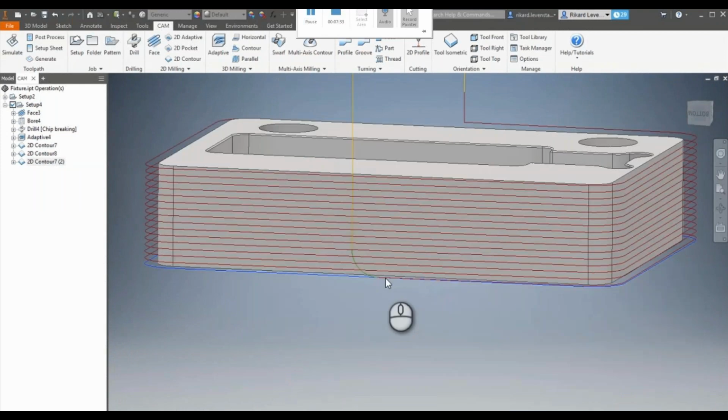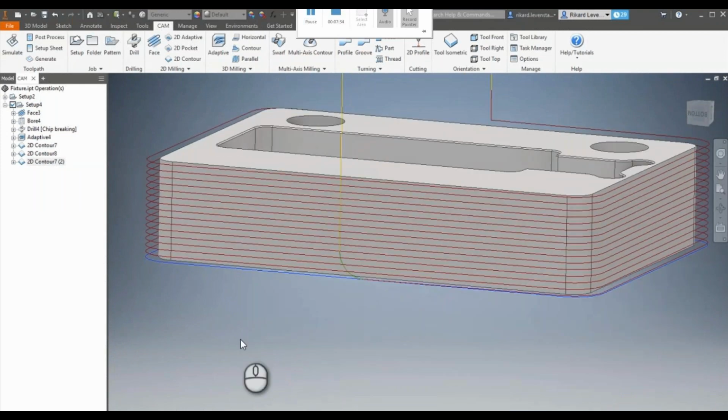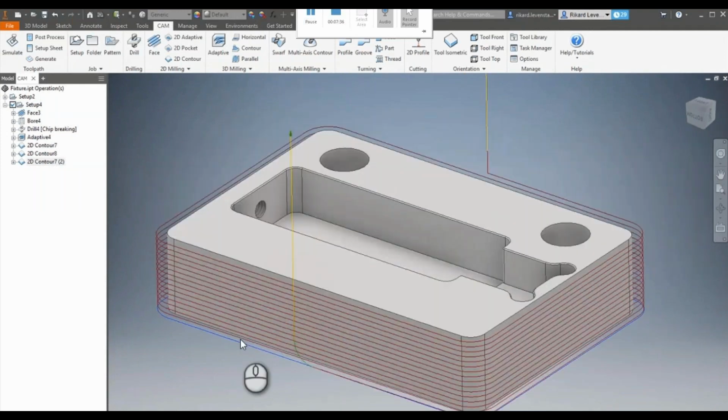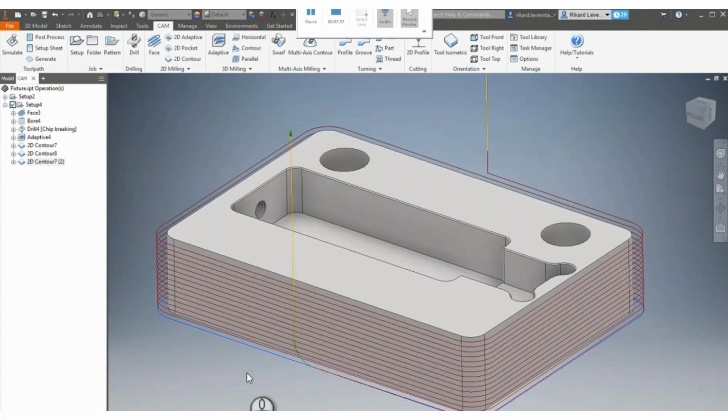So as it's coming in, the angle that the tool uses, so it goes down, and you can actually see how it's actually going to come in from the lead out. So how does it curve in with that angle, and it leads out, but the lead in is actually coming in straight. So that's something to pay attention to when you're doing it. You can actually set that up inside of the setup when you're doing that. If we move along, we find that in here again.